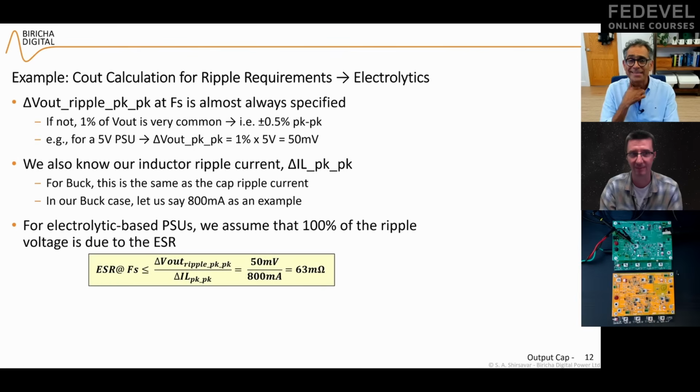Yes. But again, as with everything else in engineering, you get one advantage and you get 5 headaches, right? So having a little bit of ESR is not a bad thing when you come to design your control loop because it damps everything and it makes control loop design easier. Right? So it's a compromise like everything else that we do.